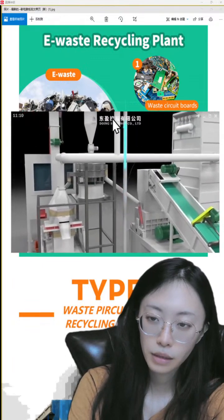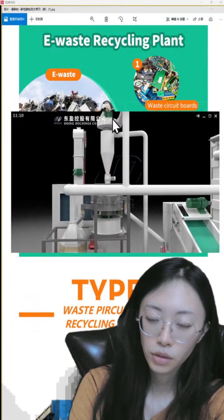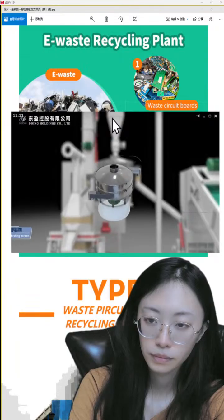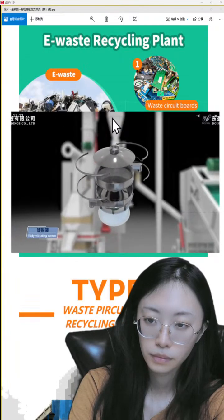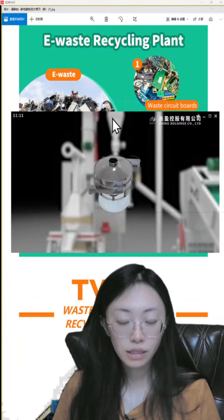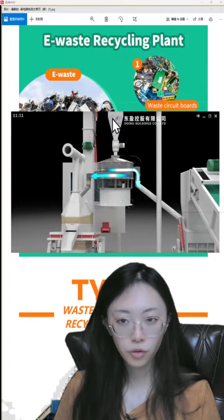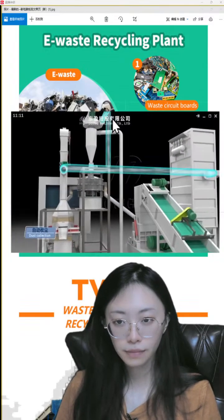And then by using this ring conveyor, they will go into the ID vibrating screen. Here's to control the sizes of the particles. They have a screen inside. If they can't go through the screen, they will go back to the hammer blade crusher to crush again.